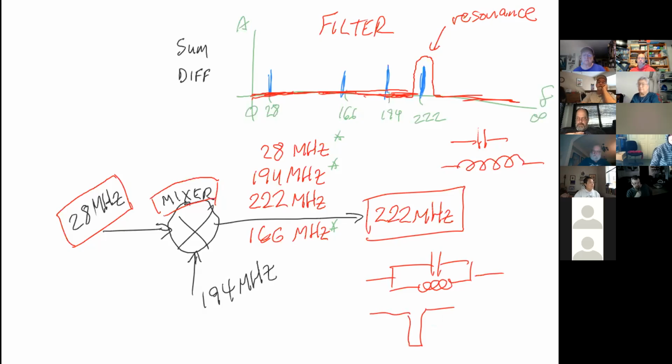And we would have a band reject, where it would basically allow everything, but at some point it would block frequencies from coming through at the resonance point. If we were to rearrange this again, like this, that would invert it, and we would end up with a band pass filter.